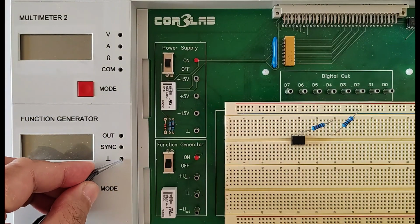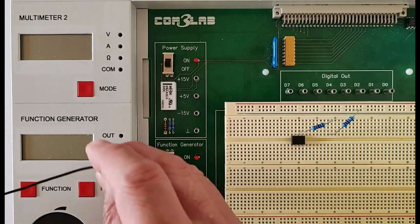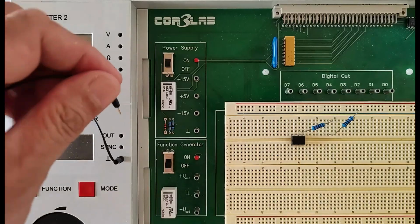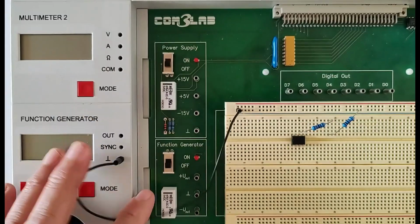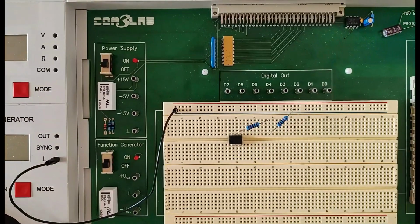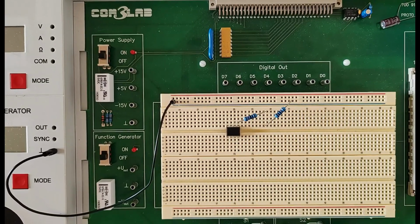The negative of the function generator would have to be connected to the blue power rail. Let me do that now. So negative function generator, or the ground of function generator, connects to the blue power rail there. Okay, now, if you can remember from the schematic diagram, what you need to do is here.